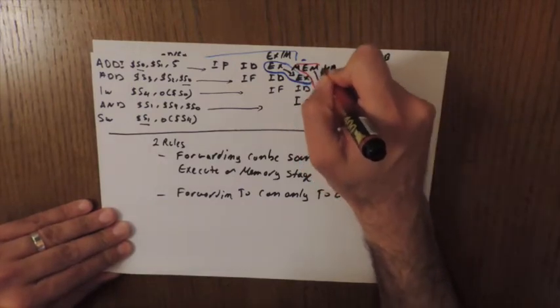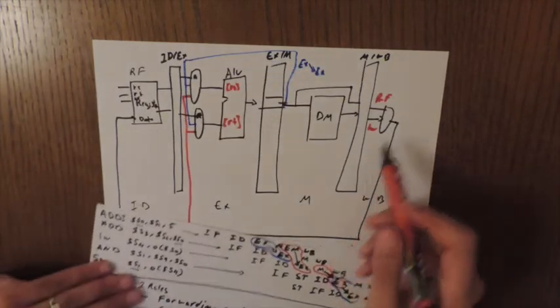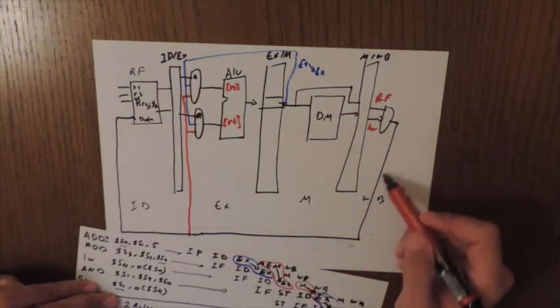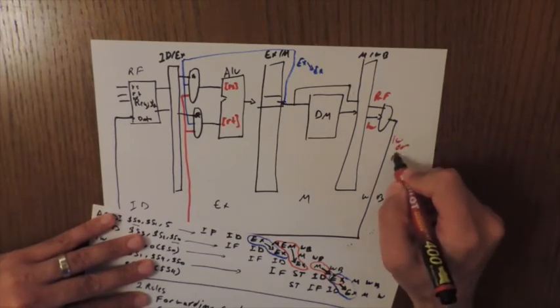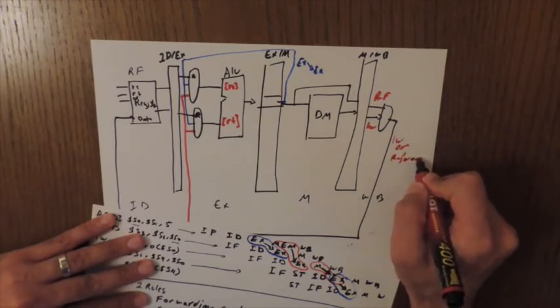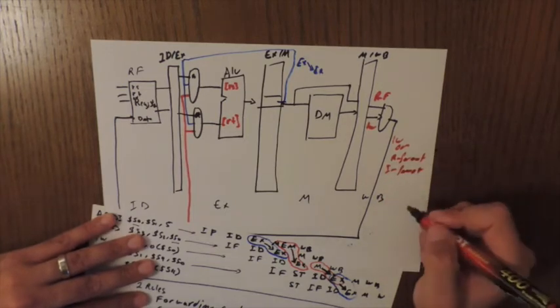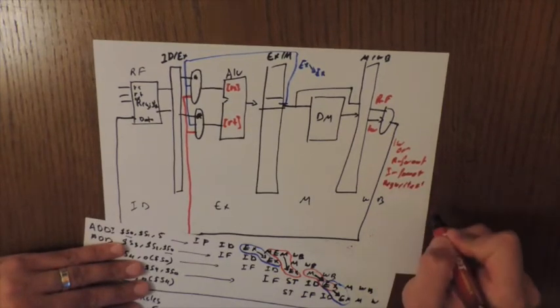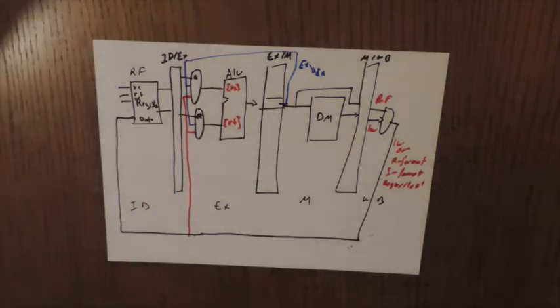So this is why, remember, here we're not forwarding the value of memory, which is fine because we're getting it from this line, which can be a load word or an R format, or can be an I format if it's an addI, for example, instruction that has register write equal 1. That means it's writing to the register file. So this is how forwarding is done in hardware.